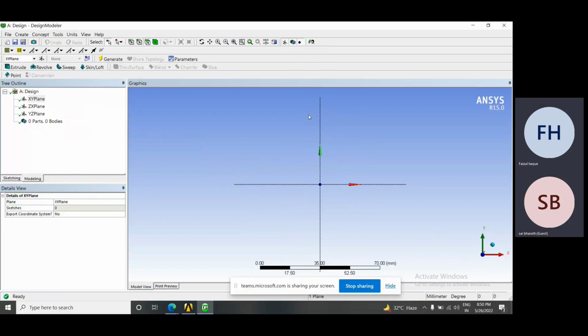Now, in order to overcome this limitation, ANSYS provides a broad range of import functions so that it can import various types of files from various 3D software like CATIA, SolidWorks, NXCAD or AutoCAD. Whatever we design in NXCAD, CATIA, SolidWorks, we can assemble also, and import the full assembly in ANSYS, and do the analysis on it.